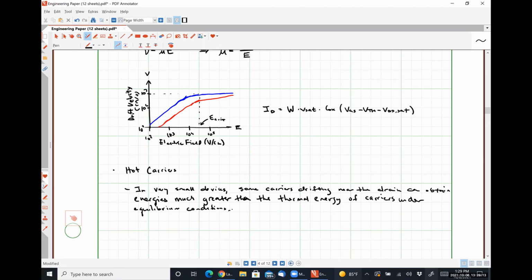I think we've talked about that in this class, but what that translates to for our models is that we can look at this as an open circuit, right? An infinite amount of resistance. So our input signals see this infinite impedance, and that's what allows us to bias everything nicely and neatly and makes all of the drain current flow down through the source, right?